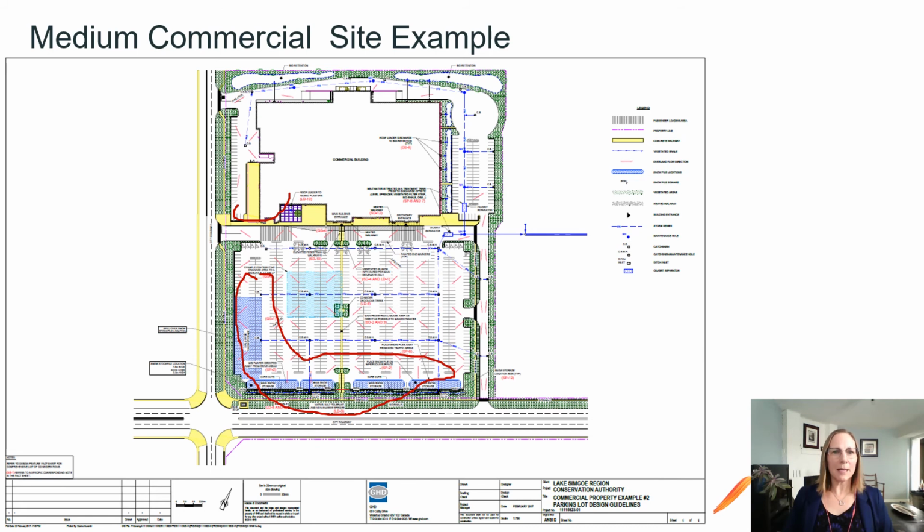The bioswale specifies that it should have native salt-tolerant vegetation. There's a single main pedestrian walkway, which goes through the center of the lot. It leads directly from the far sidewalk over here, which includes a bus stop. So I don't know if you can see that, probably not, to the main entrance of the building. So you can see that it's just very direct and you don't have any extra sidewalks that people aren't going to use throughout the parking lot.